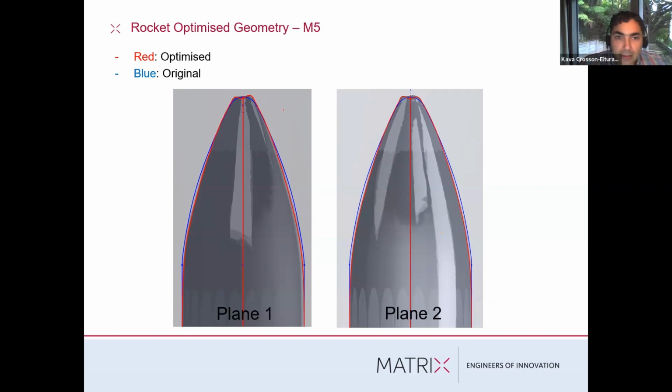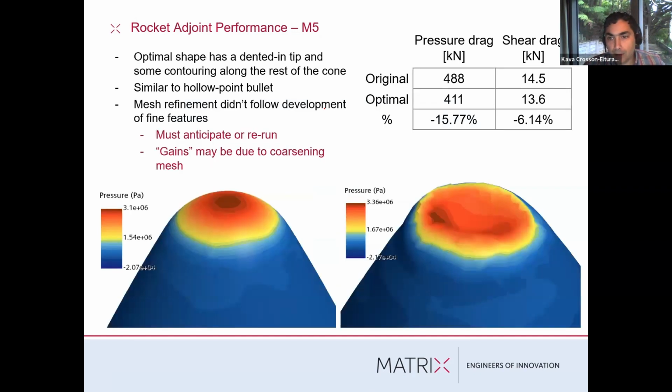don't want that. But I'm not sure how much of the drag reduction came from that asymmetry, because I haven't sort of taken this and modeled it in SolidWorks and then re-imported it in a nice clean axisymmetric way. But quite interesting to see. So ended up with about a 17% drop in drag there.